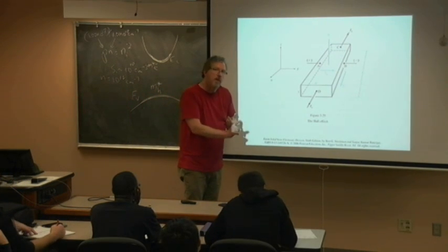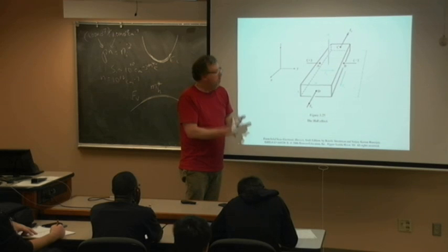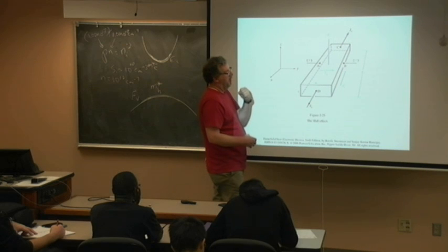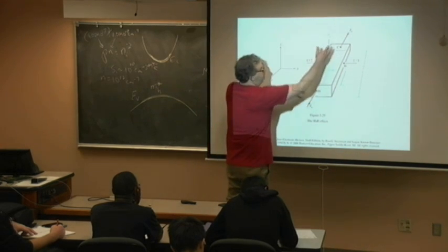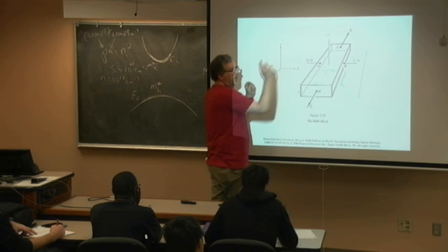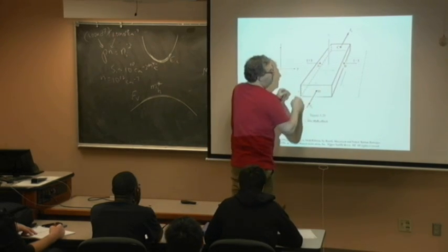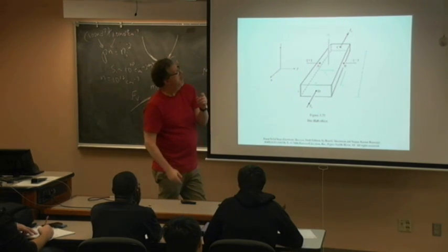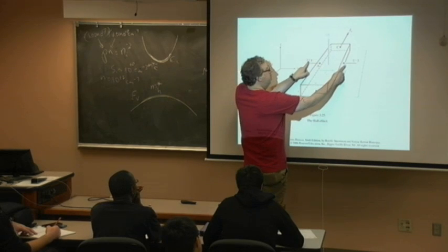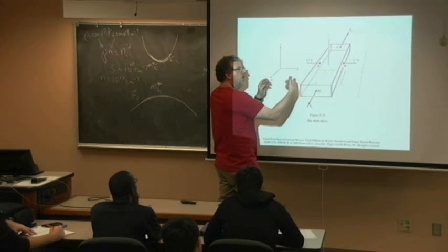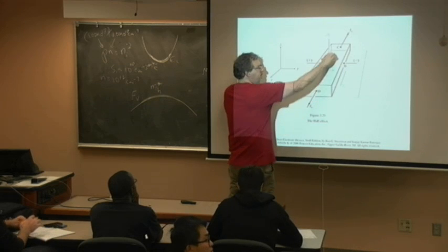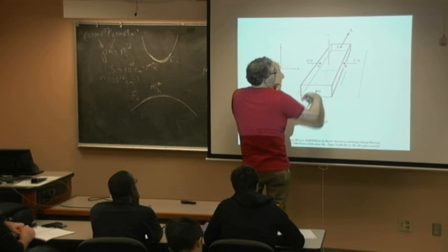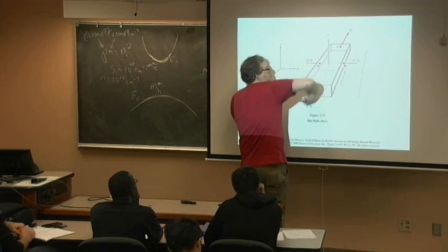Recognize I can measure mobility, I can measure carrier concentration by the Hall effect by simply having a bar of good semiconductor, and I can measure its properties by putting these contacts on it and putting a small voltage across it, sending some current through it, and then immersing it into a magnetic field. And I can measure probably between these electrodes, through the right-hand rule, I can measure the deflection. The electrons are going to come down by the right-hand rule. Okay, this is going this way, this is going that way, so it's like that.